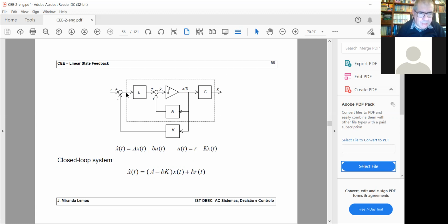So you have here some DA converter, here some AD converter, and the outside is nothing more than software in a computer that reads the data from the AD converter, which is connected to the sensors that measure the state, and you do some computations, just a linear combination of these measurements, and you feed it back. And then you write it to the port related to the DA converter.